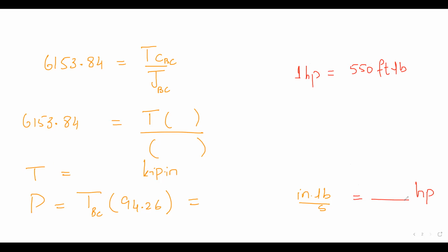For the J value, we use the inner diameter, the one that is smaller, of course, 3.75. The smaller one. So it's the extension of the same stuff that we had been doing, right? You remember that we had a hole in a simple plate. We talked about stress concentration. The dimension suddenly changed. We talked about stress concentration.